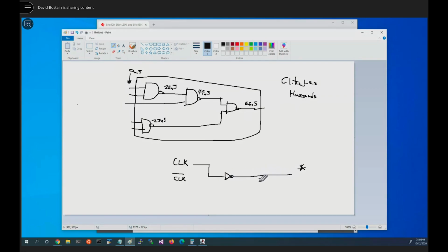That means this signal is now already 22 nanoseconds behind, because this guy would still be at 0. So what we might do is stick a buffer in here just to add some artificial delay. Remember, it doesn't do any inversion, so it arrives also at 22 nanoseconds. Now our clocks are in perfect sync with each other.